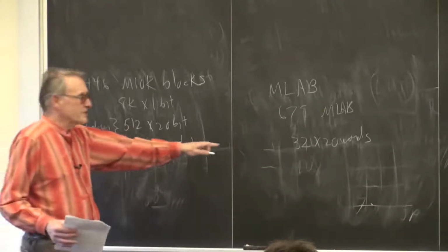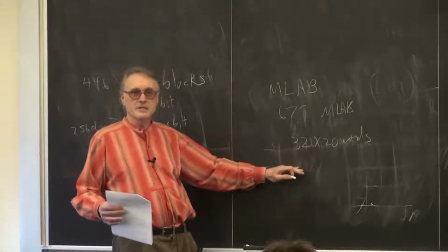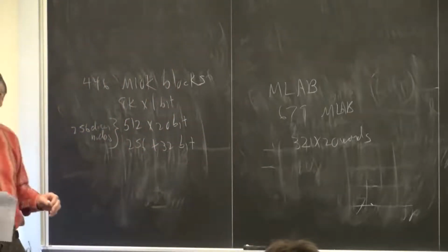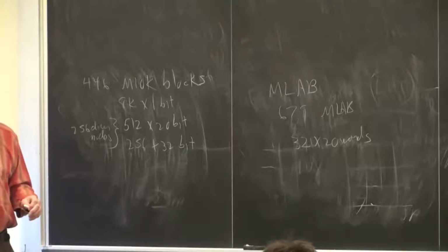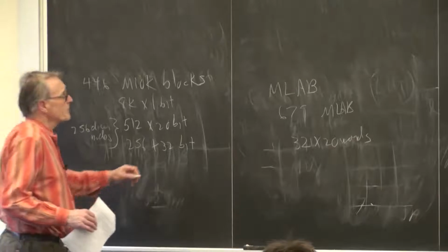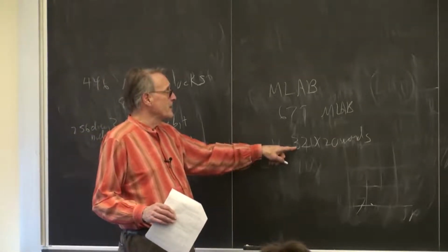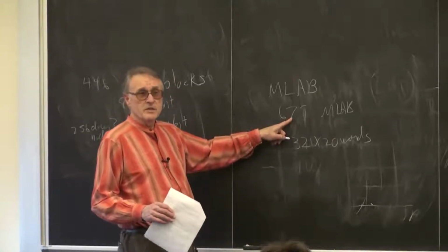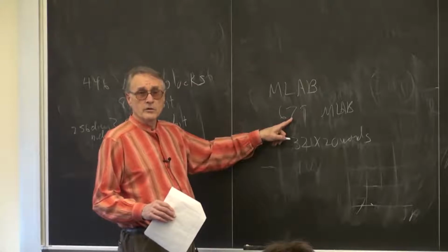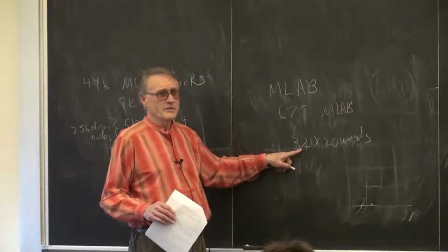That looks like about the right size. Maybe 2 of those blocks would make a really nice register set for a RISC CPU. And maybe that's how you want to write this, is as a whole bunch of stripped down RISC CPUs. But let's see, that's 10 nodes per MLab block, so you could get about 7,000 nodes if you used all of MLab memory for node state storage. But there'd be a waste here because you probably don't need 32 bits of accuracy.